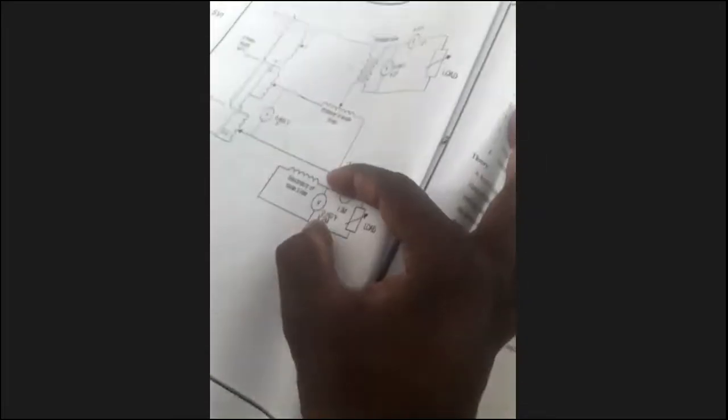Similarly, the secondary connection of the main transformer: one terminal of the secondary of the main transformer can be connected to the ammeter, one terminal. The next terminal of the ammeter can be connected to the load. Again, the next terminal of the load can be connected to the transformer 100% terminal. And then across the secondary, one voltmeter can be connected to measure the induced EMF or the secondary voltage, that is V2M. Okay.